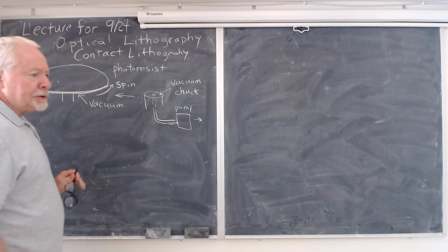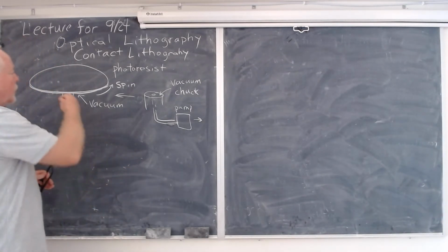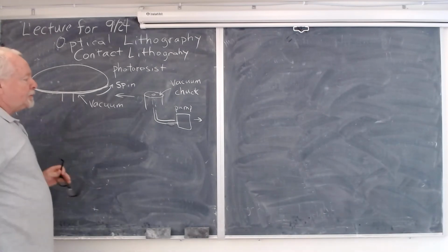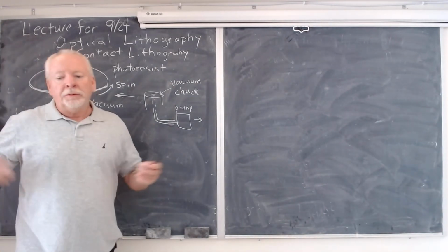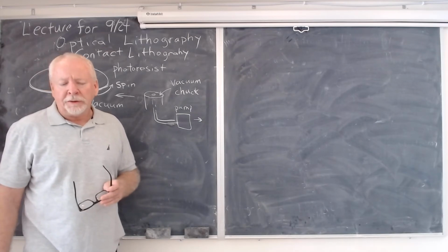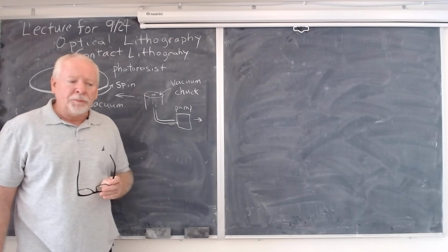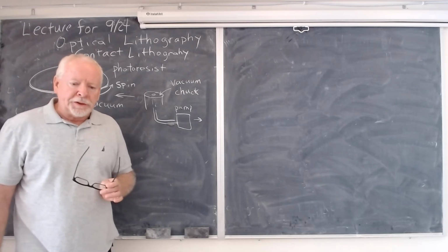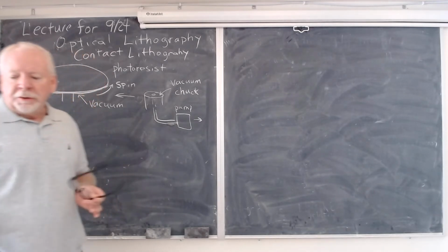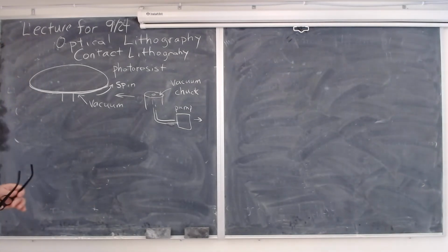There are lots of considerations. But the main thing you want is when you spin this wafer in the spinner at usually anywhere like a few thousand rounds per minute. The speed parameter is RPM, rounds per minute. So for example, if it was 2,000 rounds per minute, it would go around 2,000 times in 1 minute. So it's really spinning.